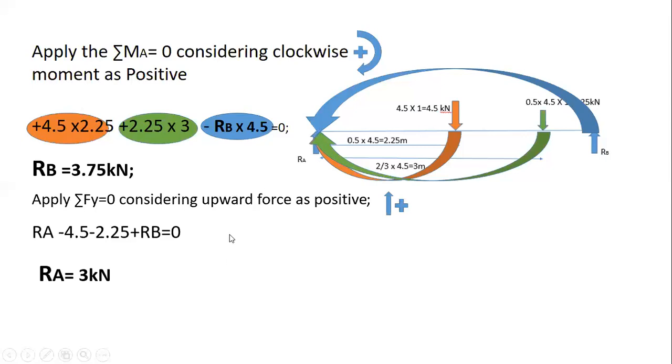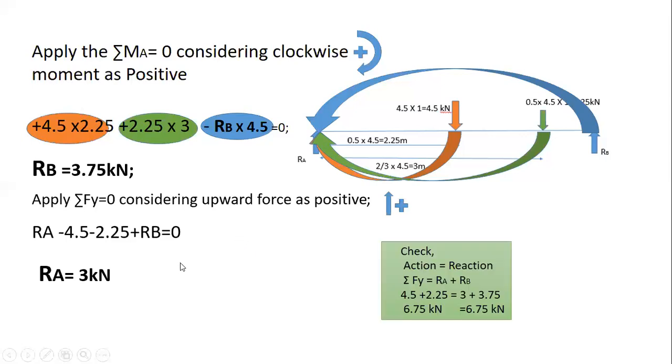If you get the negative value, that means whatever direction you have assumed, the force is acting in the opposite direction. Okay, that is the indication of negatives. Now the last step is to check whether we have solved correctly or not.